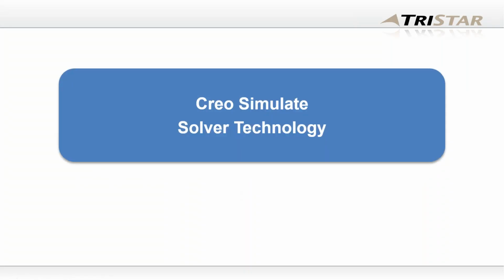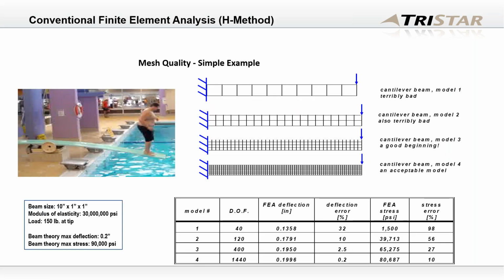So one of the biggest advantages, before I show you a quick example on Simulate, is the technology itself, right? If you look at the traditional finite element analysis, which is typically most of the softwares are H-based, the mesh density plays a very important role in the accuracy of the solution. In other words, the experience of the user plays a very important role in getting an accurate solution. So I have a simple cantilever beam situation here. The finer the mesh, the more accurate is the answer and less is the error.